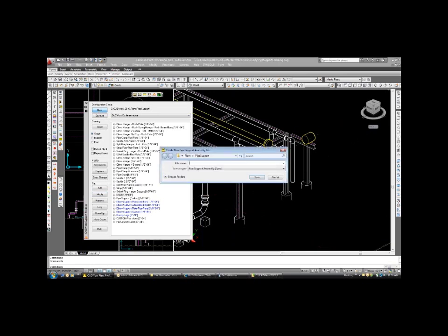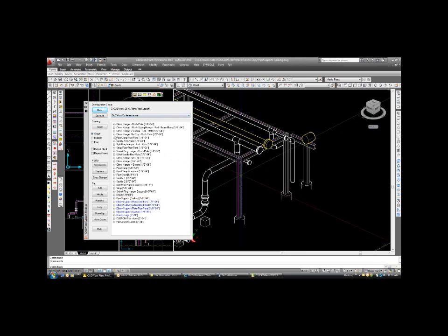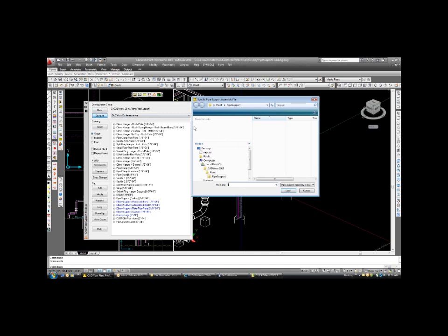I would give it a name and what I wanted to call it, say Project 1001. So whatever project this was, plant number 10, we just save it here and it would register it into our pipe support directory. Or we can take an existing one, save as, and then just modify it. See here it puts it into that one particular directory.